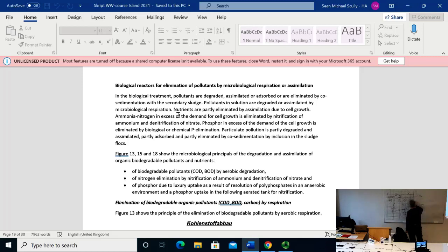Because this is, again, this ratio, I told you, the 0.5 is from 100 grams, and we degrade 80 grams of COD. Only 40 grams end here, but the ratio, how they measured it, because it's a measured value, is 0.2 grams of nitrogen assimilated for 100 grams of COD degraded.